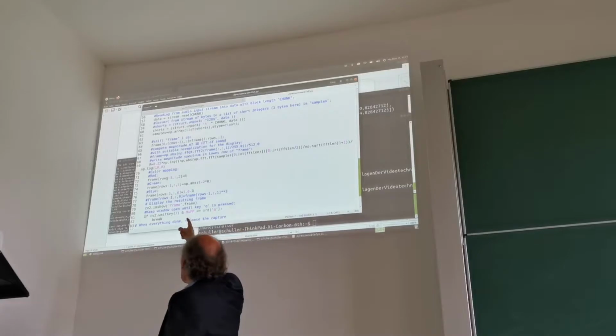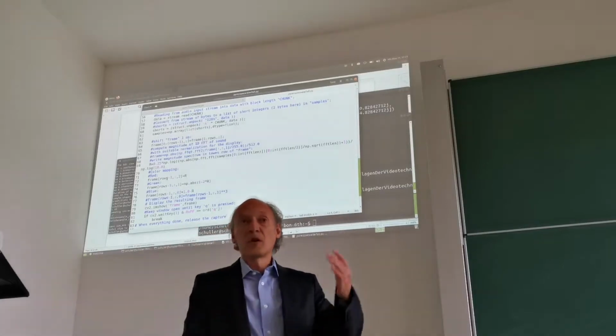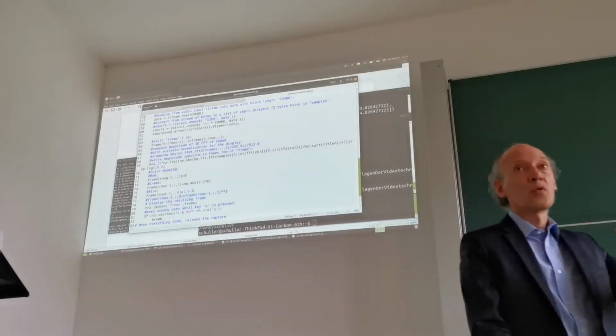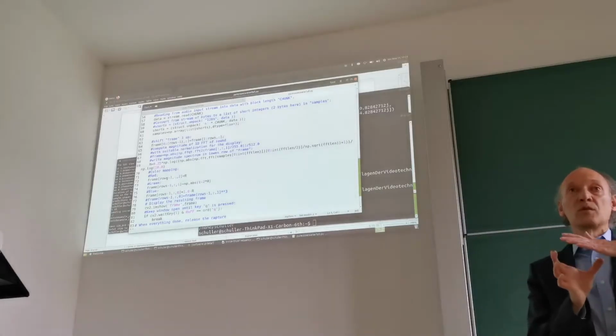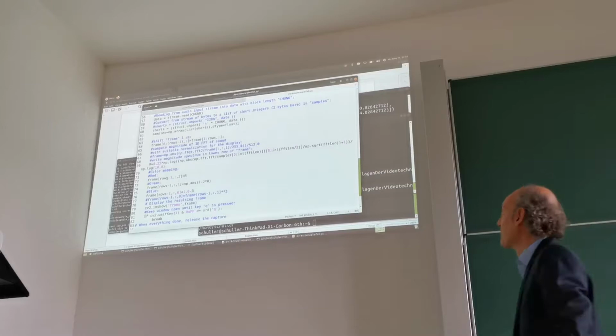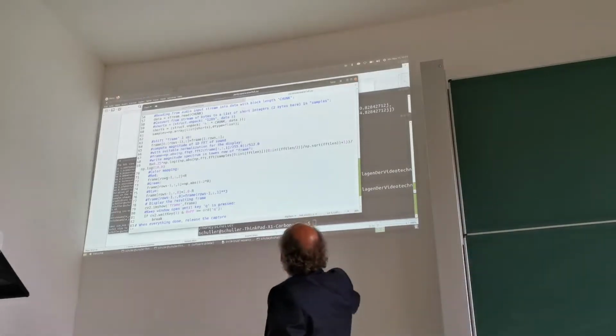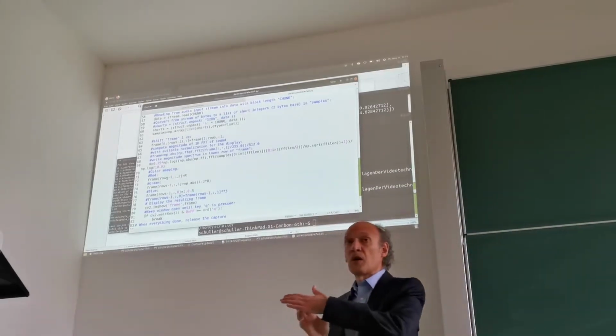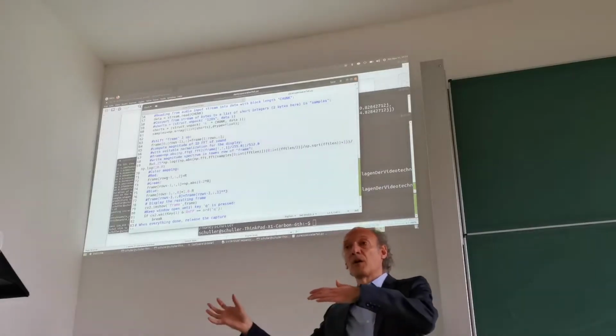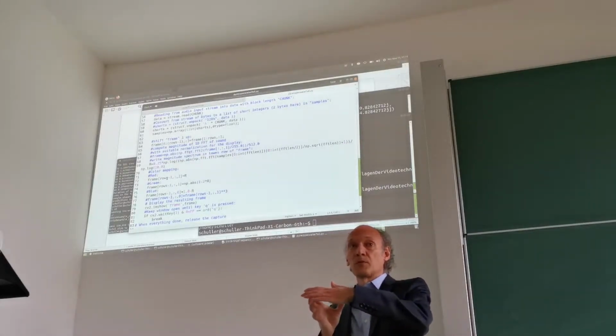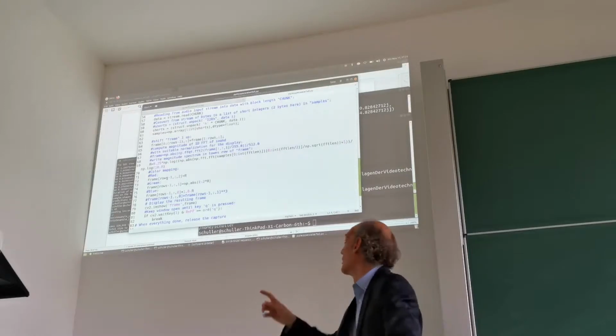So, in this case, I'm always assigning the lowest row the output of the FFT, which is an array of length 512. I'm only using the first half, because I know that the upper half is symmetric, so I can simply drop it. So I'm only plotting the lower half of this FFT.